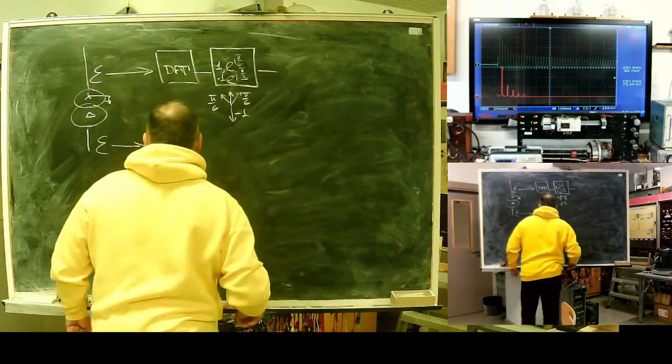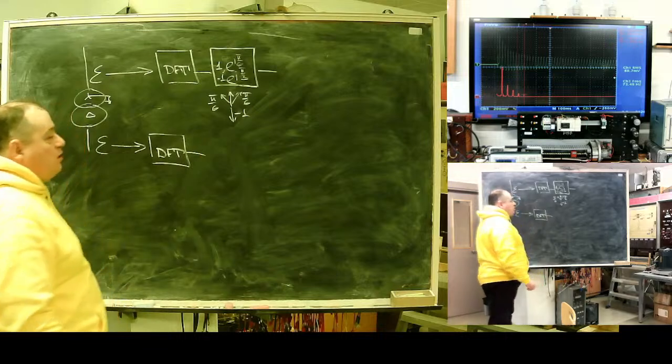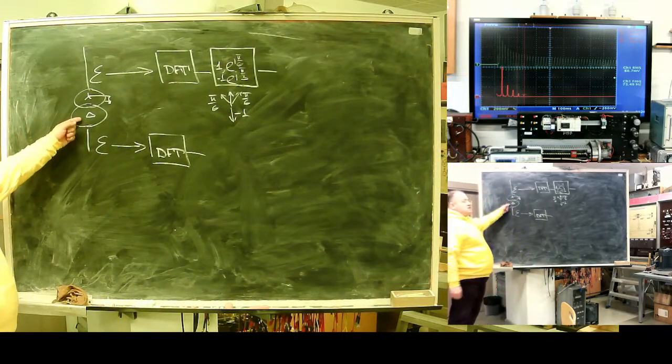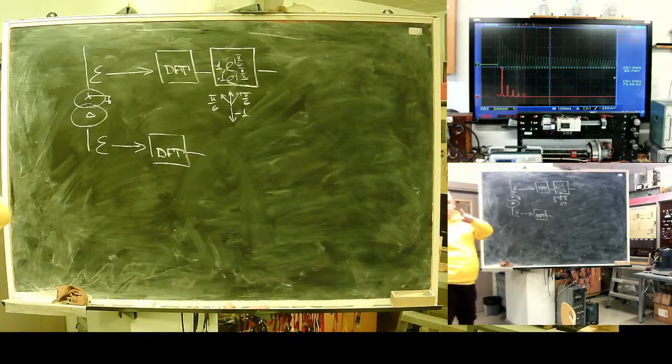transformer rate. Also, on the opposite side, another thing can be done. See, these large transformers usually have built-in ability to switch taps, so the transformation rate is adjustable. It's done to control voltage.